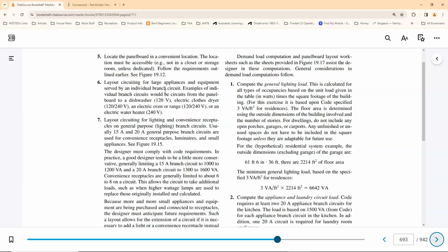Other folks, though, don't mind spending the extra money to separate the lighting circuits from the electrical circuits. And this is sort of a convenience thing, especially if you've ever had to find the breaker box if you trip a breaker. If you trip a breaker in a situation like the first one I described, the lights go out too, right? But if you're concerned about tripping a breaker, or a GFI or an AFCI, and you want to make sure the lights stay on in that scenario, the entire lighting circuit could be separated.